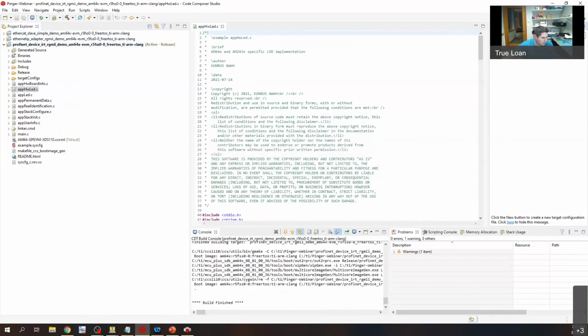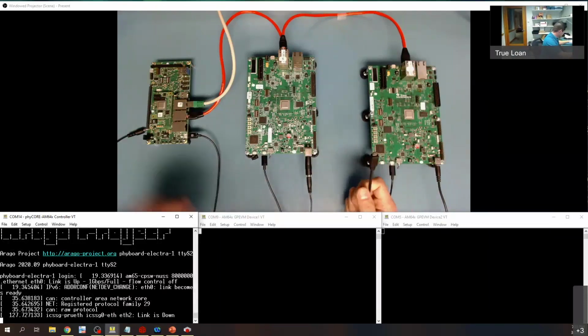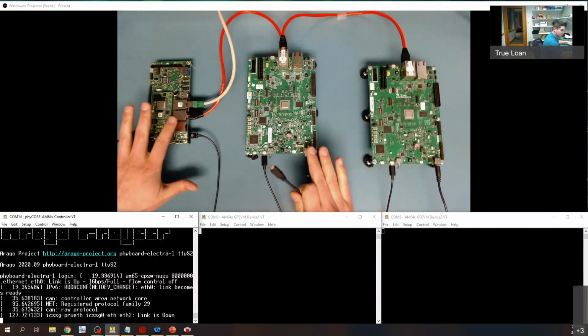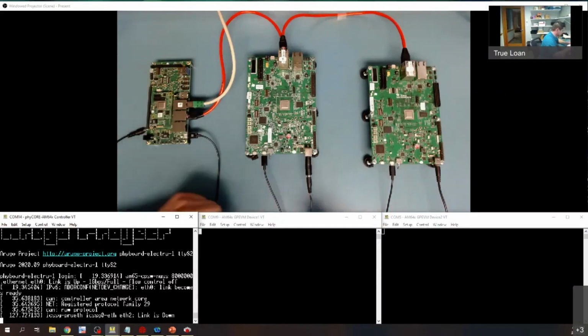With the project built, now I can go ahead and launch a target configuration. Before I do that, let's take a look at the hardware. I'm going to load this firmware over JTAG, so I'm going to need another micro USB port. What's nice about the two designs featured on my table today is that there's an XDS110 JTAG debugger integrated into the board itself.